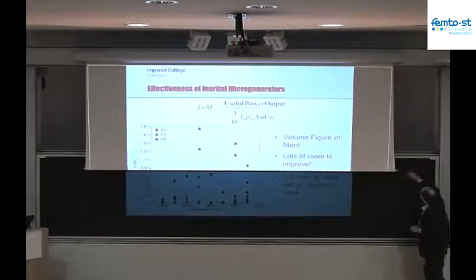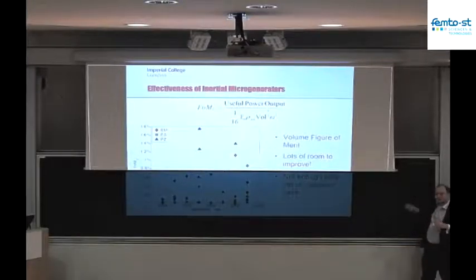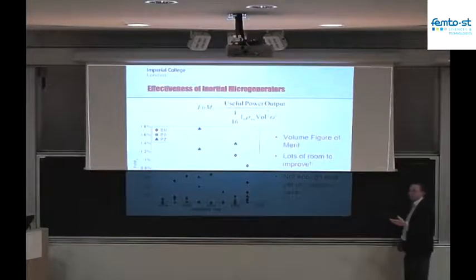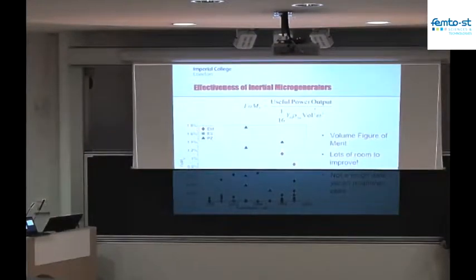And if I can move only between my mass, between two boundaries, if I move sinusoidally between those two boundaries, I end up with a motion like this. If instead I add in a little bit of third harmonic and I pull the tops off here a little bit, I can then increase the fundamental value a little bit more and hit the end stops. And crucially, as long as I've got a fundamental force at a particular frequency or a fundamental motion at a particular frequency, any harmonic content that I've got in there doesn't actually contribute to the generation of real power in a positive or a negative sense.